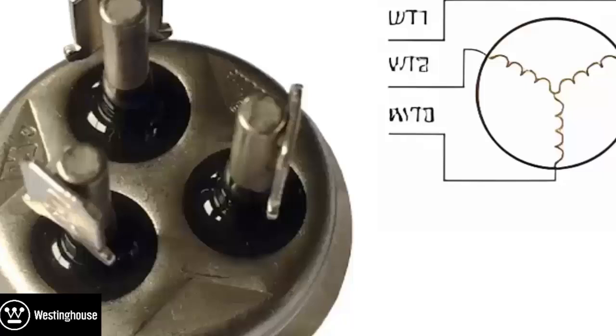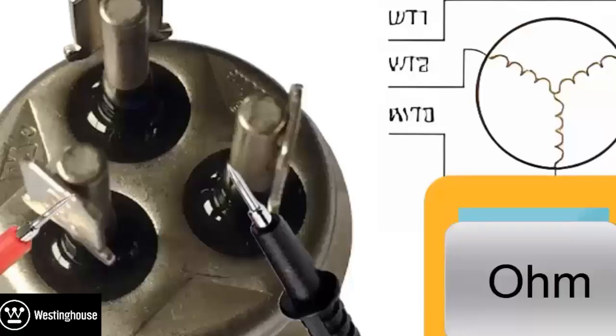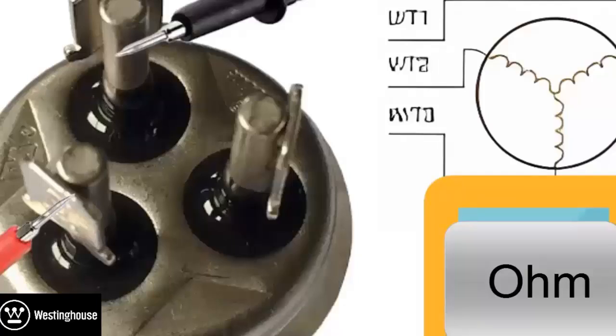2. Perform resistance measurements on the coils. 3. Even if no obvious issues are detected, internal coil faults may still exist. 4. In an inverter compressor, resistance measurements should be very close or nearly identical across all tests.